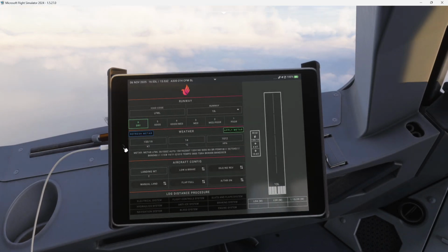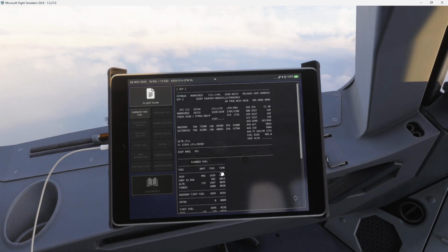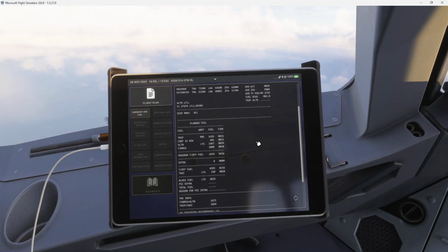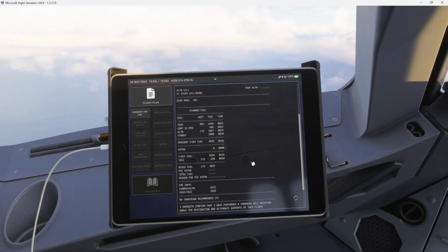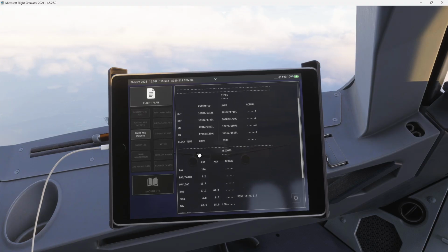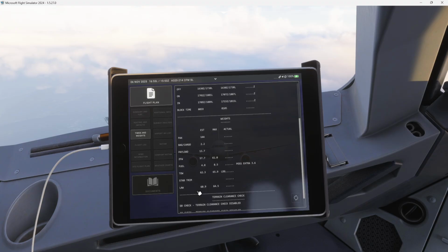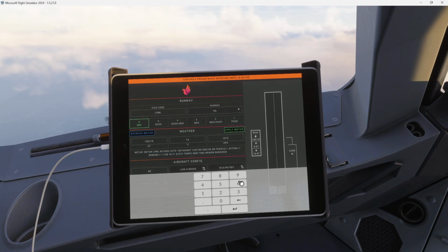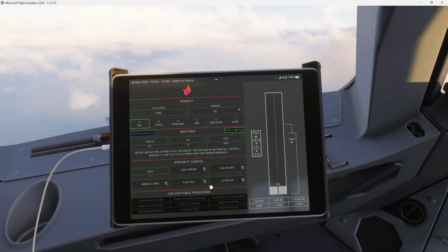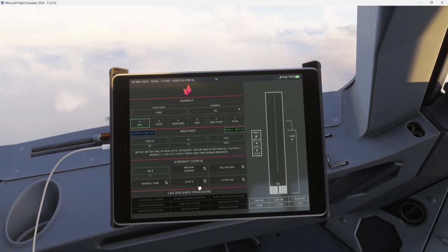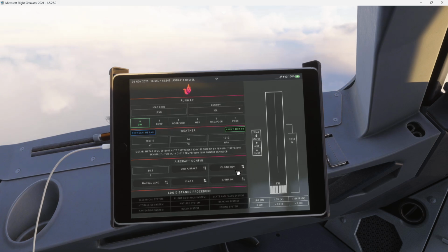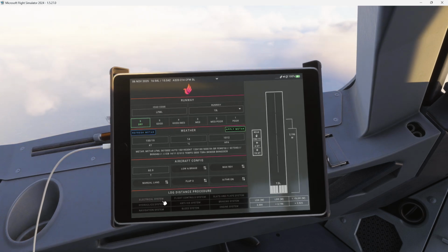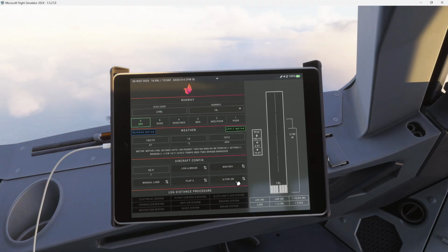Not I think, I'm pretty sure, because in this weather it's terrible to get inside without anti-ice. I will go flaps 3. Brake low. Either reverse, max reverse. That's fine.